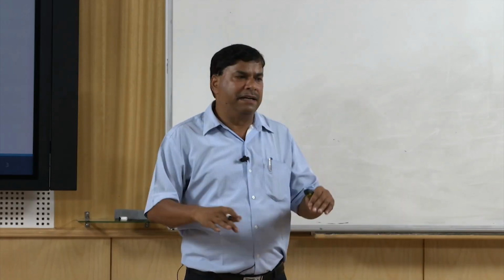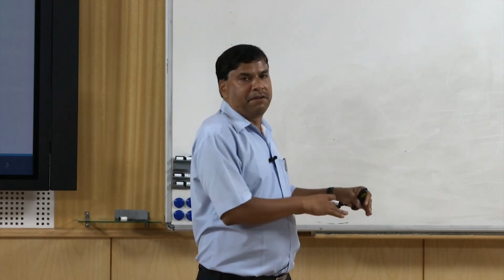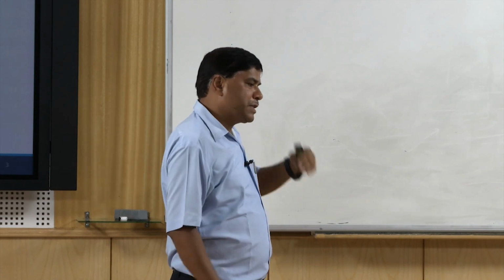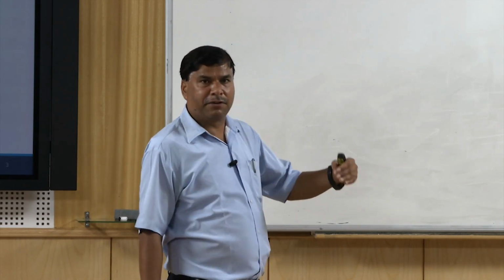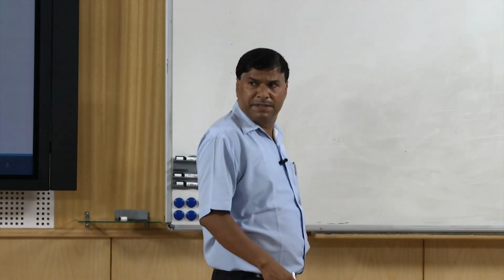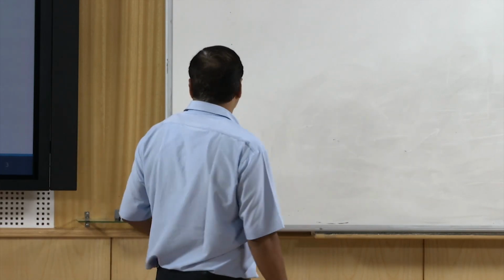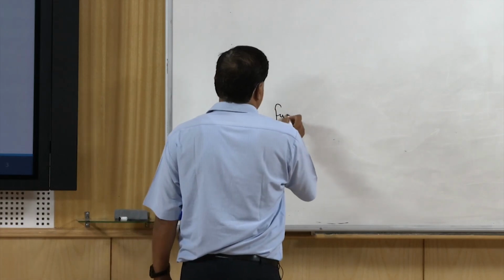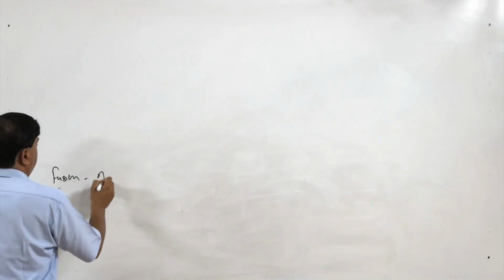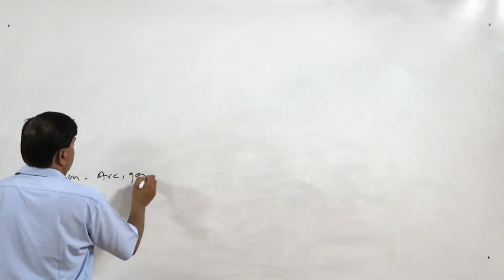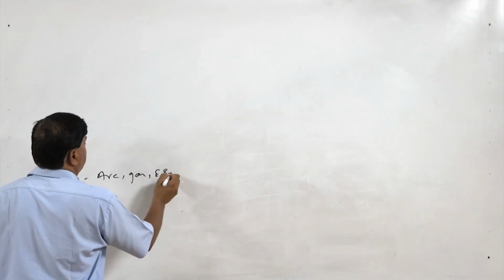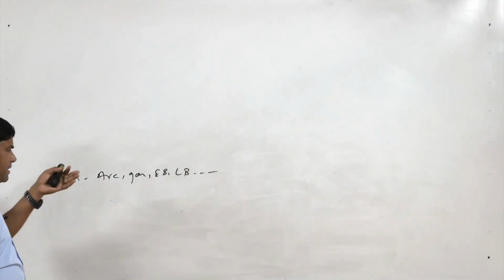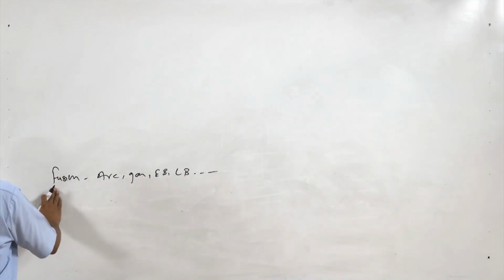So, all arc welding, gas welding, thermite welding, laser welding, electron beam welding, wherever the fusion of faying surface is achieved for developing the weld joint, they are categorized under the fusion welding processes.